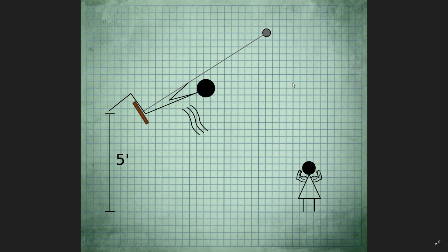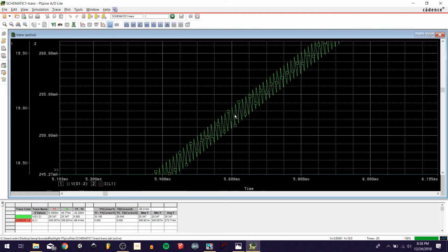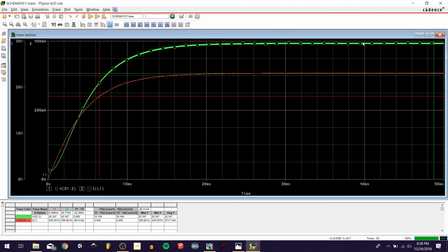So even though she's not that strong, she can get her dad up to 5 feet. Similarly, even though I only have 3 volts, by leveraging the properties of the inductor, I'm able to use that 3 volts to slowly push things up, push by push by push, until I get it to 30 volts. And it levels off there due to several steady state conditions, those equations that we satisfied.